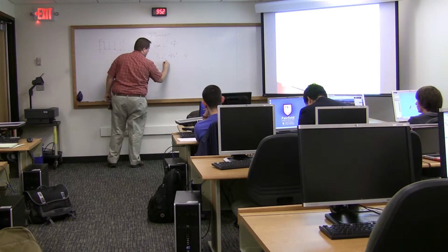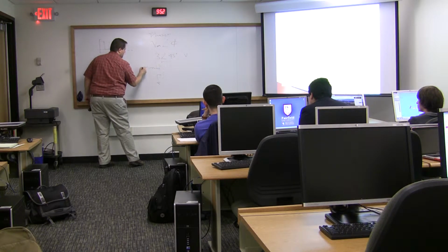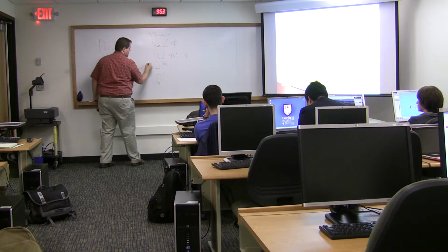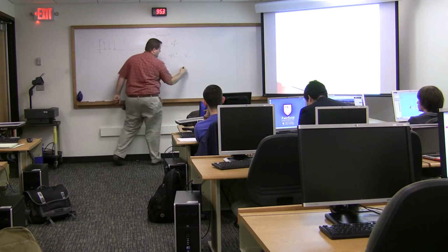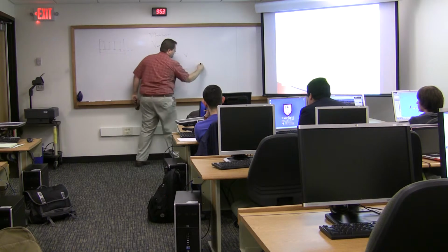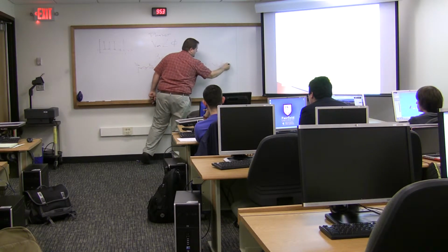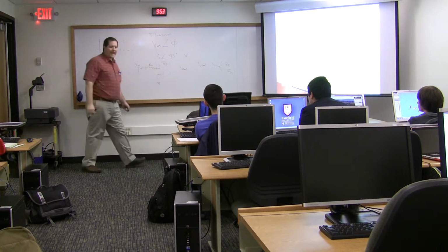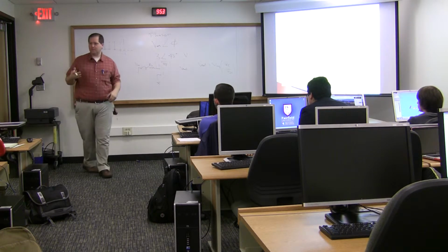If I have a simple inverting op amp configuration, like this, right? We've said, oh, this is the feedback resistor, this is the input resistor. So if I have V in and V out, V out is just V in times, in this case, the gain, negative RF over Rin, right? So we've seen this concept before.